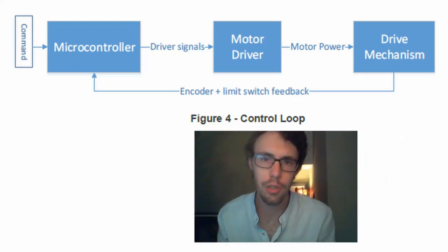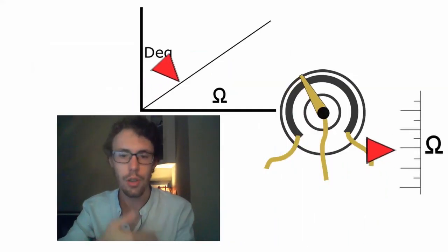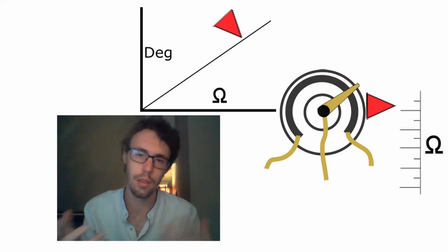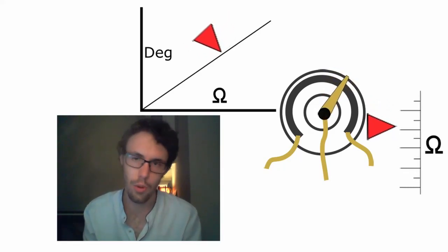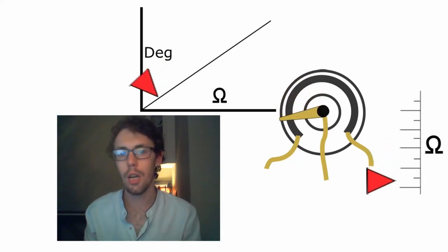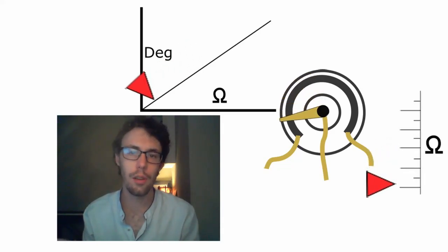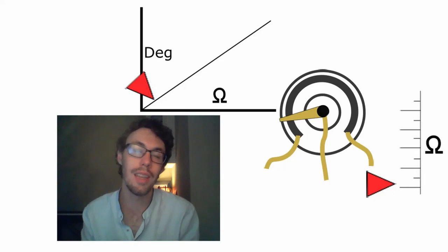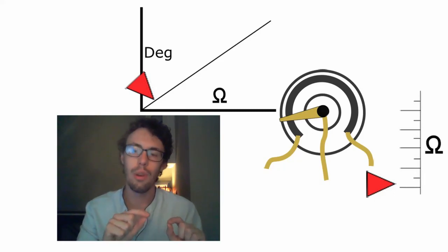So you can have a potentiometer, which is just a resistor. So more resistance means more left or more right. Less resistance means less left or less right. And then you digitize the resistor input through an analog to digital converter, which most microcontrollers have, and then you estimate its value. So the downside of using a resistor is it's not very linear.